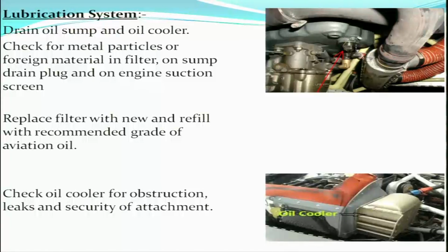Apart from the filter, we also need to check the sump drain plug and the engine suction screen. After replacing the filter with a new filter, we refill the oil system with the recommended grade of aviation oil.